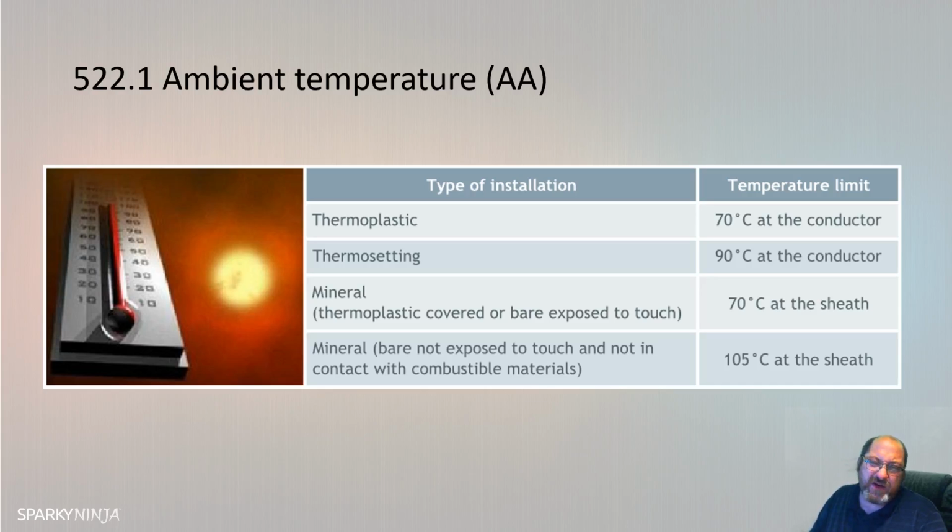This is also a previous kind of question that I've seen before, the recommended guidance. So if I was to say what external influence category requires IP, I don't know, 4X, you can then say, well, that's not liquids, that's solids. So you go to AE. And when you go to AE, which is the solids, you can see the recommendation of IP4X belongs to AE3. So it's just understanding how the external influence categories bounce around like that.